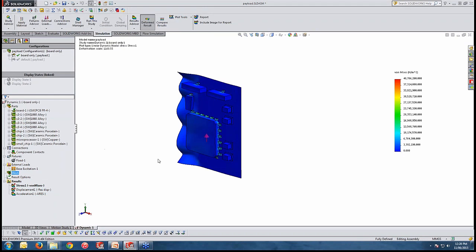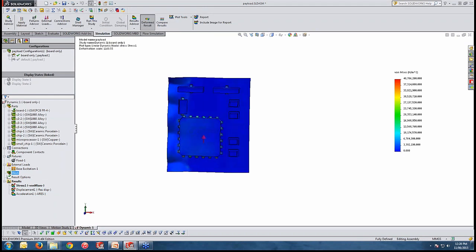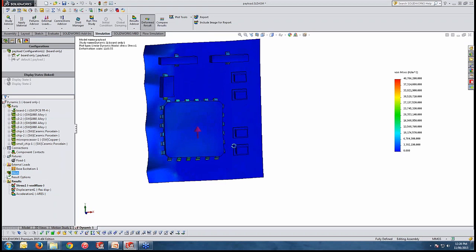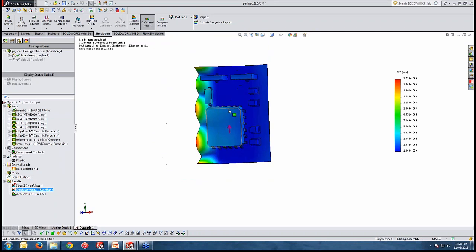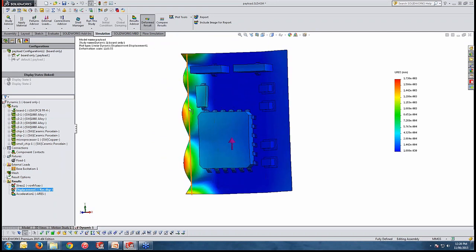So you can see the max and minimum element size, mesh quality is high, and simply nothing is reporting wrong. And since the study is finished, now we can review the result in any aspect we want. First, displacement. As you can see, we recorded the displacement happening on the edge of this circuit board. So this is where the maximum displacements are happening, and we can read the magnitude of the displacement, which is away from its fixture.